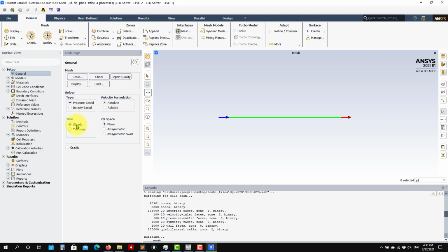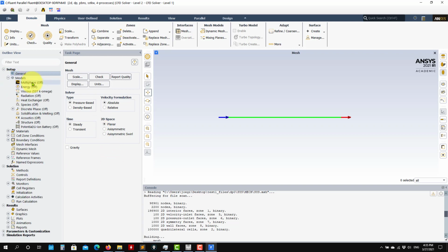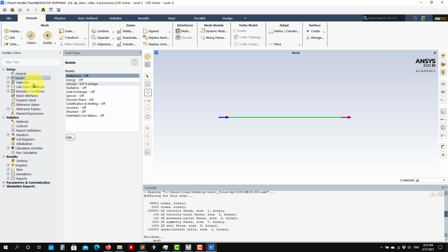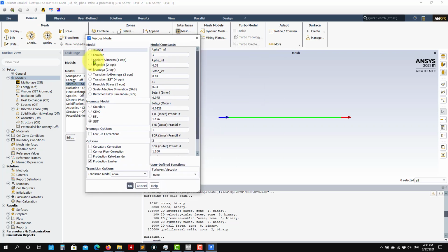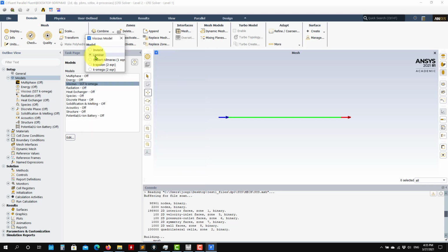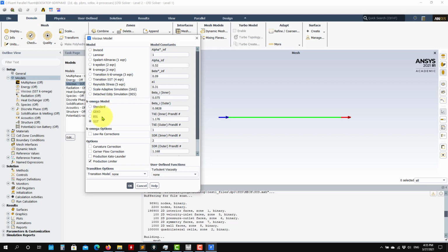We are going to run a steady simulation, and we don't want to use any of this axisymmetric option. You have more options, but leave it like that. Then Models is where you enable models. For the moment, we're focusing on turbulence modeling. Go to the Viscous tab, where you can select models. If you want to run the laminar solution, laminar means no turbulence model, select it there. By default, you're using the k-omega SST turbulence model, which is the one I recommend, and you see Fluent proposes by default the most general one.